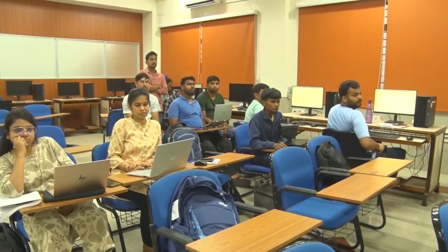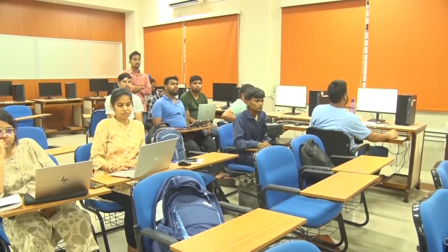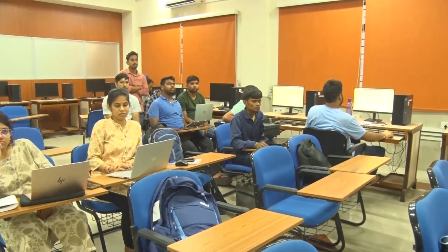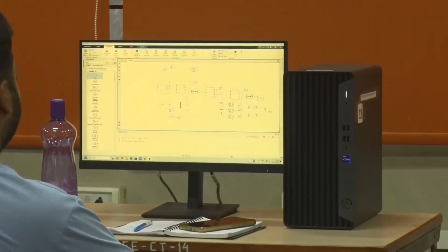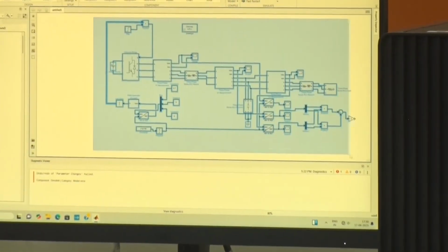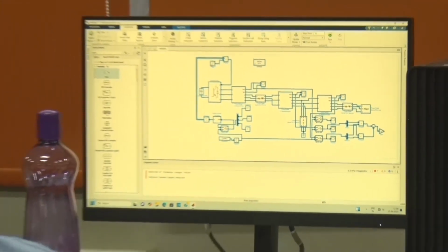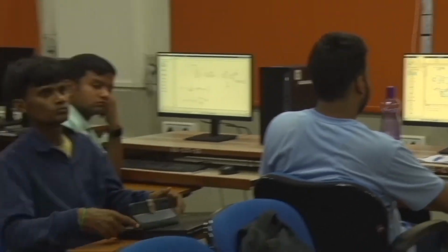Because it's a single inverter, there is no issue of instability, because there is no relative oscillation. Oscillation always occurs with respect to some other. So far I am just showing you a single inverter, so there will not be any oscillation. But this may happen if you have two, this value may be unstable. Then you have to reduce the amplitude. Okay? So this is what we have done. We have now implemented the droop part.